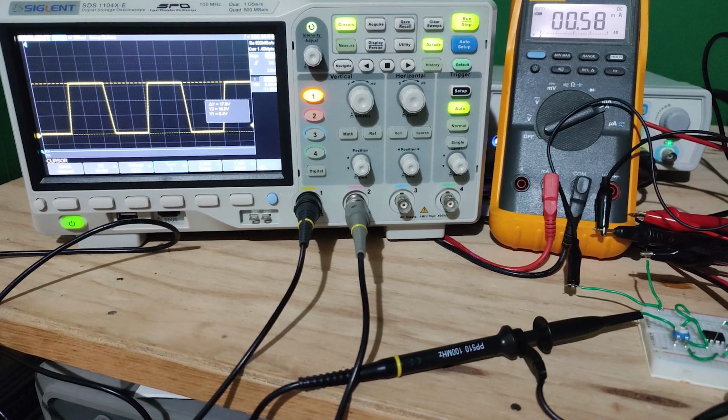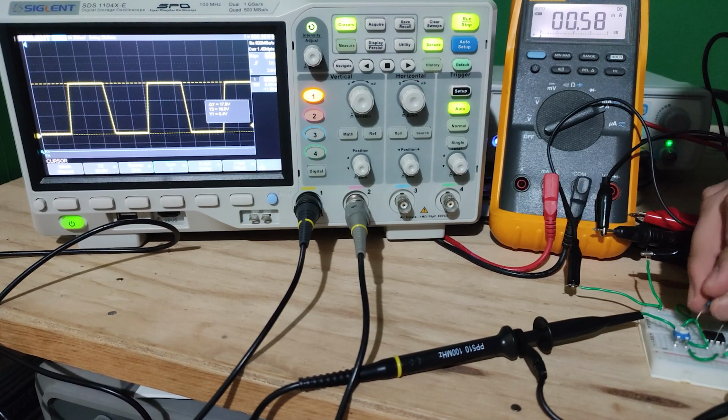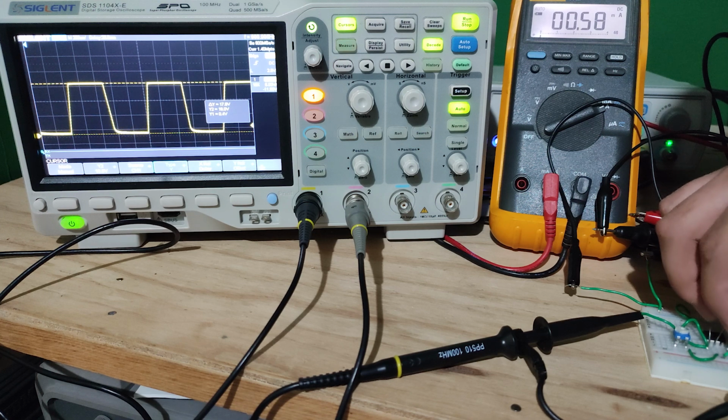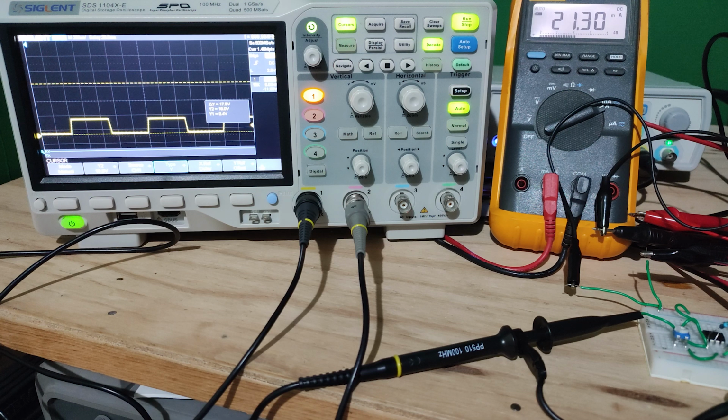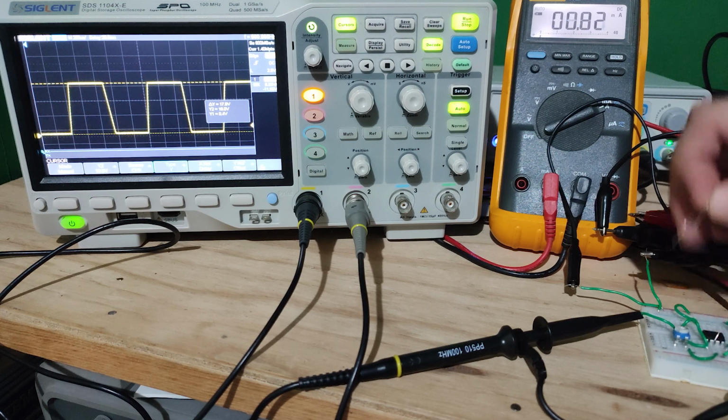So it's not easy to burn the output of an op-amp, but it is possible. So avoid connecting high loads. We can see how if we put a 21 milliamp load, the output voltage drops quite dramatically because we have a high output resistance. So beware of this. If you need to control higher loads, use transistors, use other methods. Op-amps are not meant to control loads.